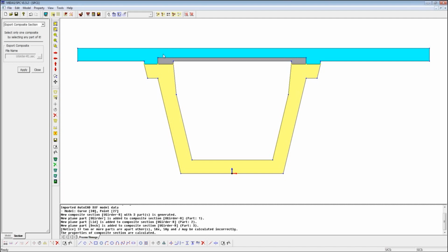So the best thing that you can really do is make different DXF section drawings with different types of haunch heights that you are working with, and you can just throw that into the section property calculator. In one sheet, you can fit in as many sections as you want, compute all the properties, and then throw it back into the software for running the analysis and doing a scenario analysis, I would say. I hope that answers your question, David.